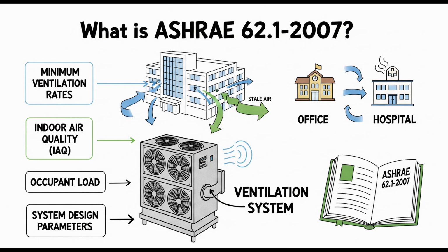It sounds like this standard is mostly written for new construction or major renos. What about older buildings? Appendix G gives some guidance there. The main insight is that applying the entire standard retroactively to an old building might just not be practical or feasible. Okay. But the principles of the standard, checking outdoor air, proper filtration, controlling sources, maintenance, those absolutely can and should be used to guide improvements in existing buildings. So you don't have to rip everything out. Generally not for simple repairs.